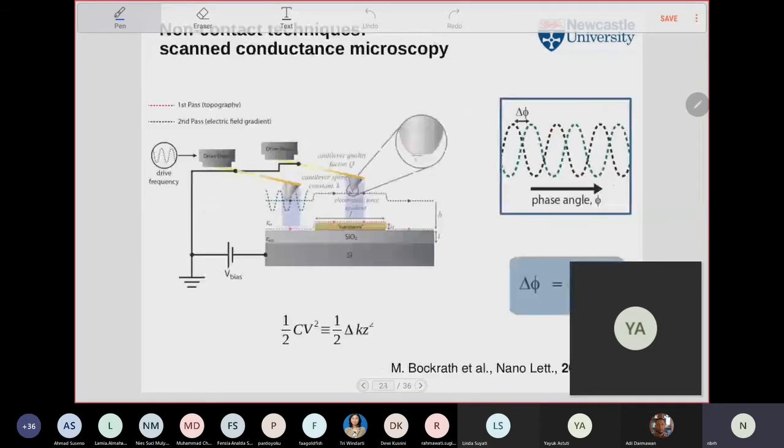And finally, I'll show you one last measurement technique. So this one is less familiar, but it's the easiest of all of the techniques to execute, because you don't even need to make contact with the nanowire to do this. It's based on something called lift mode in AFM. So I've sketched here how lift mode works in AFM. So you have the cantilever, which holds the tip which touches the sample to generate your image, and this is oscillated by a drive piezoelectric.